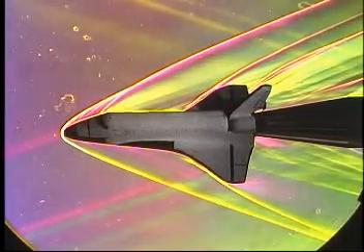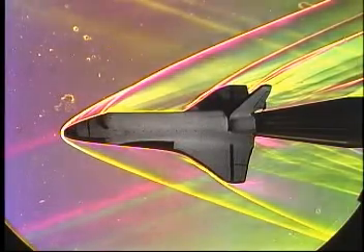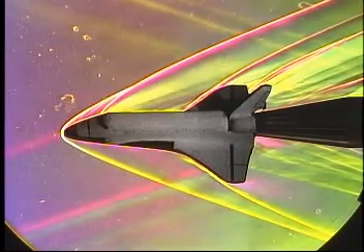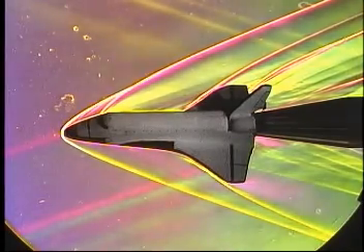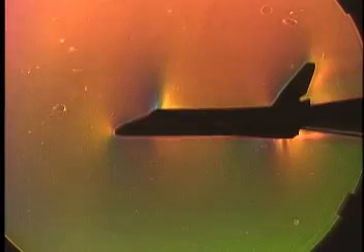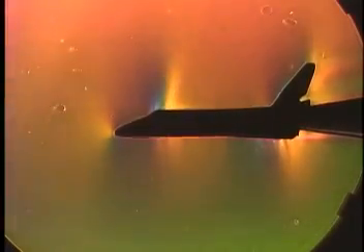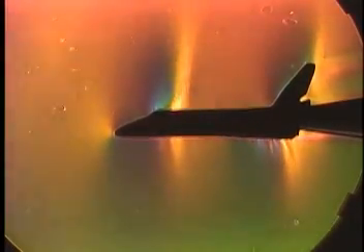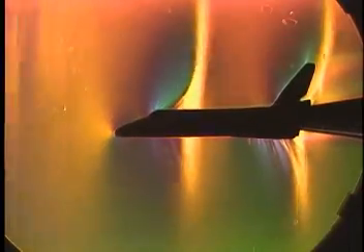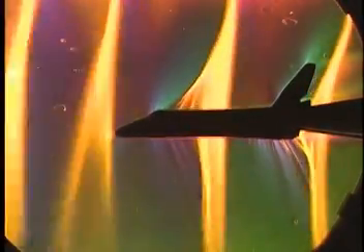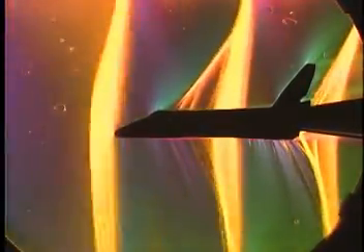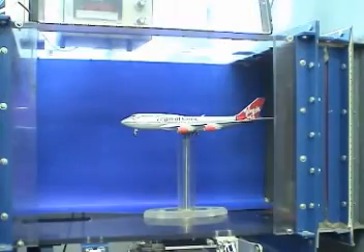On the other hand, some flight vehicles break the so-called sound barrier and fly at supersonic speeds, or Mach number greater than 1. When the Mach number is around 1, as in this transonic wind tunnel test of a space shuttle model, small speed changes make a big difference in the flow pattern. This leads us to the powerful concept of similarity.